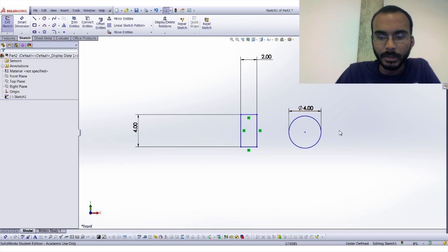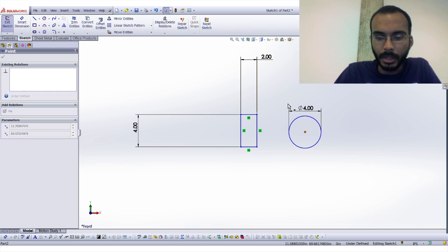Let's see, what else did we not talk about? When you are sketching, if you drag a part around, it'll snap to different points. So if you want to put something on the corner, or if you want to move it differently, you can. It'll try to give you center lines. These little dash lines that it drags out will show that you're centered with that rectangle. So you can drop it in the center really easily.